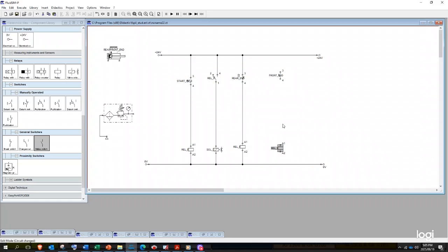All right, before I start connecting the components that we use to retract the piston rod, we're going to first finish our components for advancing the piston rod. So our relay 0 connects with this changeover 0 for our push button. And then this rear end limit sensor or limit switch that senses the rear end position is connected to a relay. However, you can't have a relay and not have a changeover switch, because those two are a pair. They go hand in hand. So what do you have to do now?